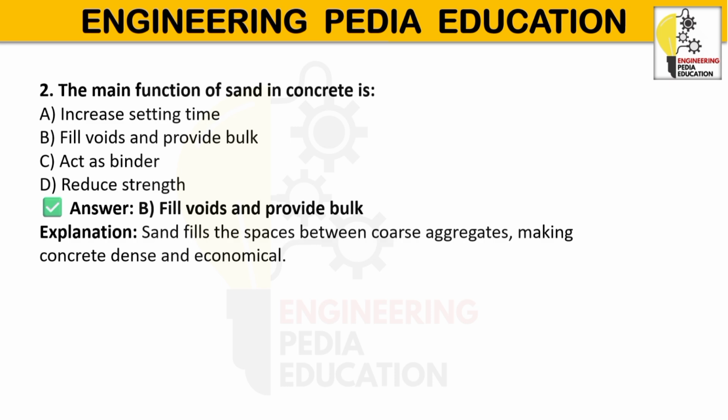Workability improves, shrinkage and cracking decrease, it helps to increase the strength and durability, and also manages the ecological balance. So what are the requirements for good sand? Clean, free of organic matter, well graded, silt content limited, durable, hard particles.